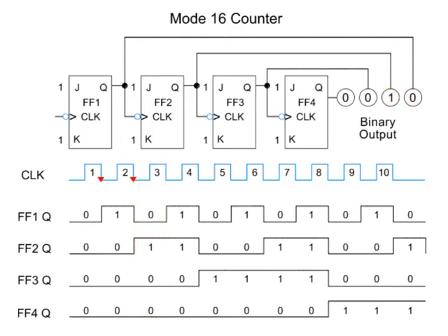The counting continues, with each flip-flop output triggering the next flip-flop on its negative going pulse. The 1's position, or A, must change its state on every count. Thus, flip-flop 1 must toggle for each clock pulse. The 2's position will change its state half as often as the 1's position. Thus, flip-flop 2 will only toggle half as much as flip-flop 1.